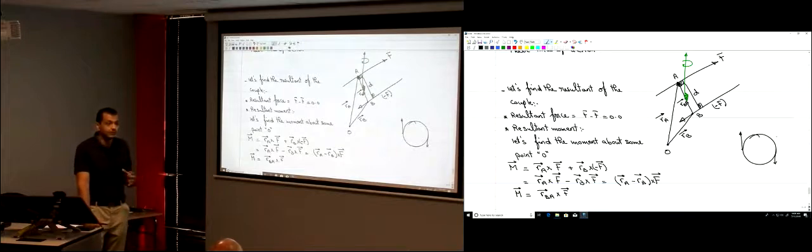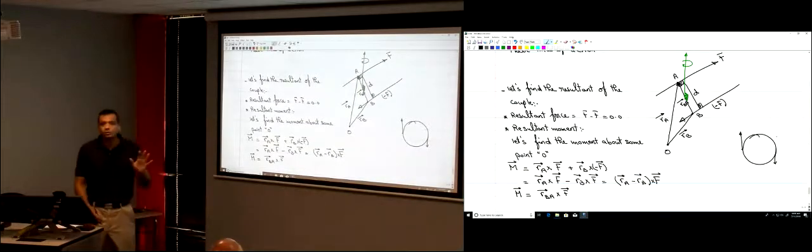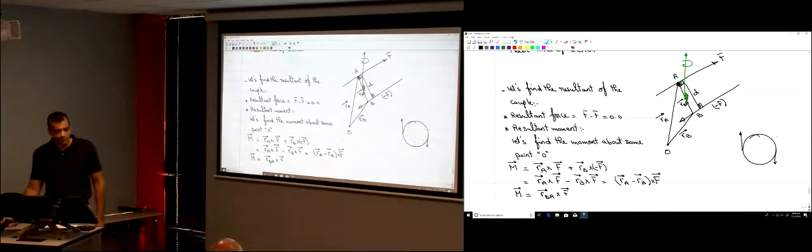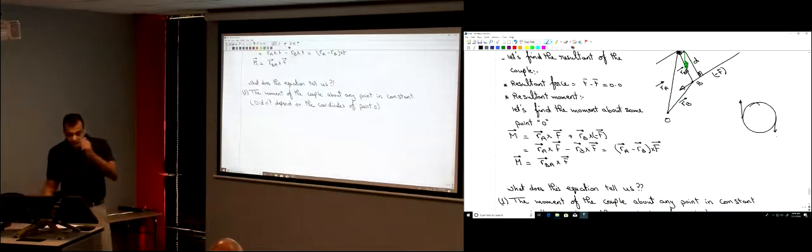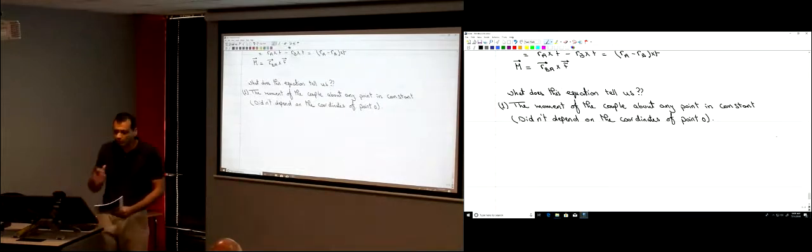So it's constant. So for a couple, I don't care about the point. We said moment. When I say moment, what point, right? Moment about what point. But for a couple, it's the same. I don't care what point it is. It's always going to be the same magnitude. So that's the first important conclusion. For the couple, the moment is constant. It has nothing to do with what point.